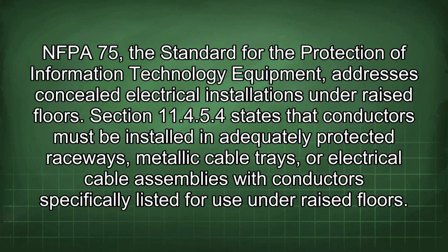NFPA 75, the standard for the protection of information technology equipment, addresses concealed electrical installations under raised floors. Section 11.4.5.4 states that conductors must be installed in adequately protected raceways, metallic cable trays, or electrical cable assemblies with conductors specifically listed for use under raised floors.